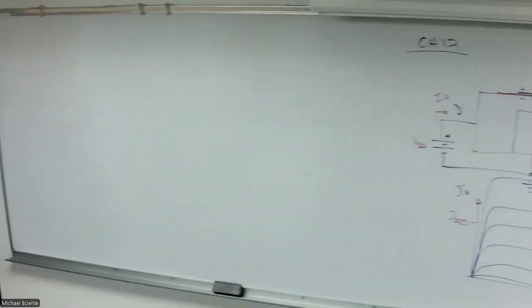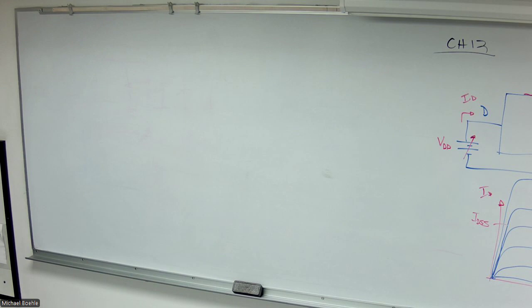Now, this has the same low noise characteristic. Yeah, it must, because I have no forward bias junction. It's the forward bias PN junction and the recombination of holes and free electrons that makes that noise. Is this any better or worse as a low noise amplifying device than a JFET? I'd say they're probably comparable. But this is more expensive. JFETs are pretty easy.